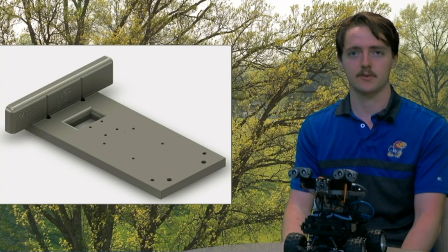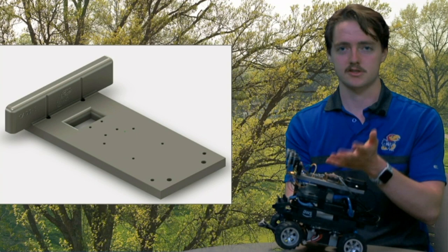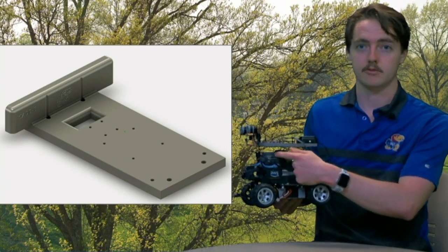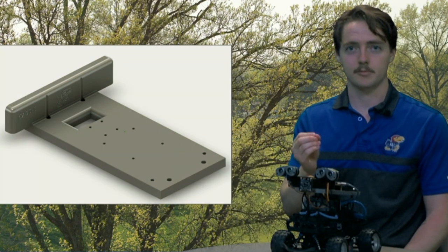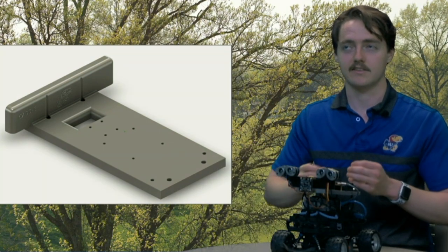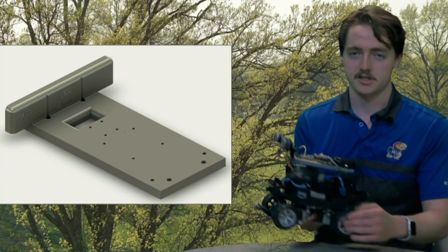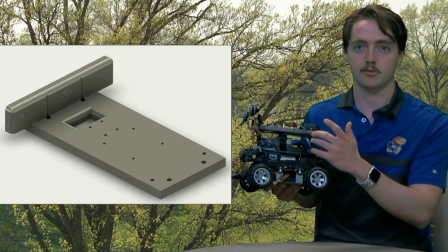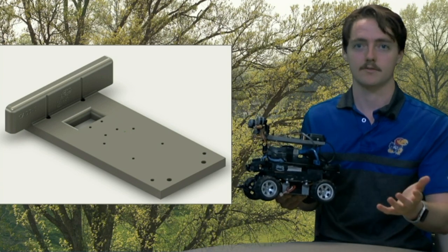CADD-E's physical system is comprised of two main computers, as well as a bunch of sensors. The first computer is the Raspberry Pi right here. It's responsible for handling all of the sensor data. It reads in the sensor information, processes it, and then sends it over a ROS topic to the other computer, which is this onboard computer on the DeepRacer, which is responsible for running everything else, including the path planner, the controller, and the UI, etc.